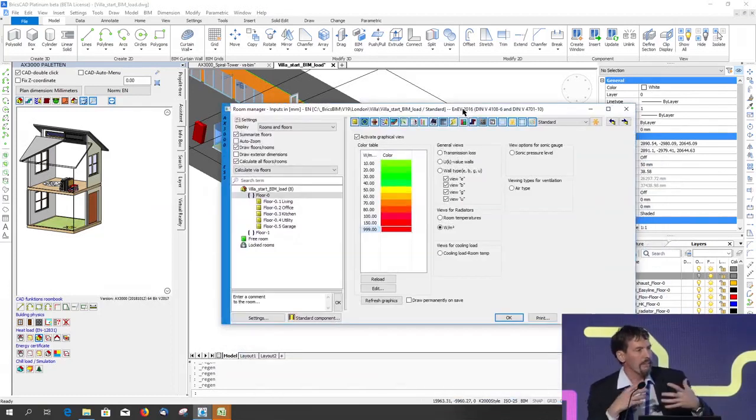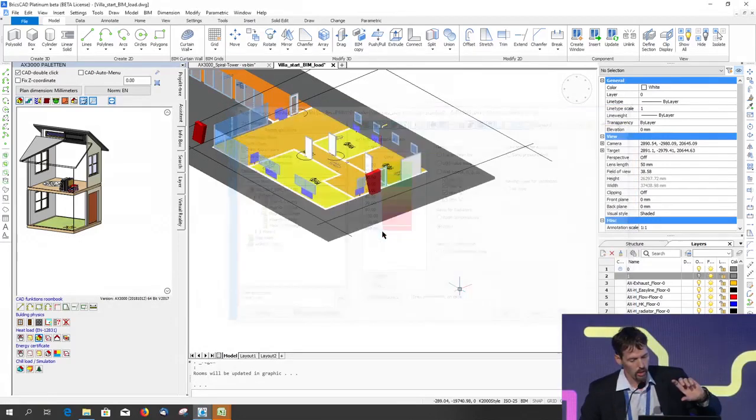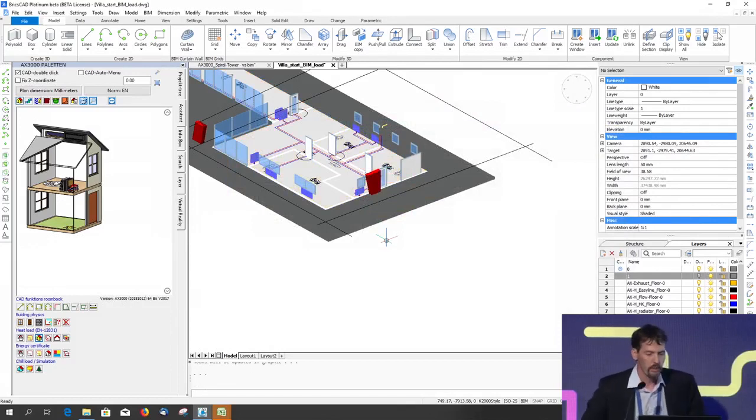Okay, this was static calculation. I've used the coldest temperature outside, the hottest maybe inside. To go one step above, it's also possible to make building simulations. So what is the difference? For a standard load calculation, you take one temperature, maybe the coldest of the day, and you calculate this value. For a building simulation, you use an entire year, and you need the temperatures hourly.